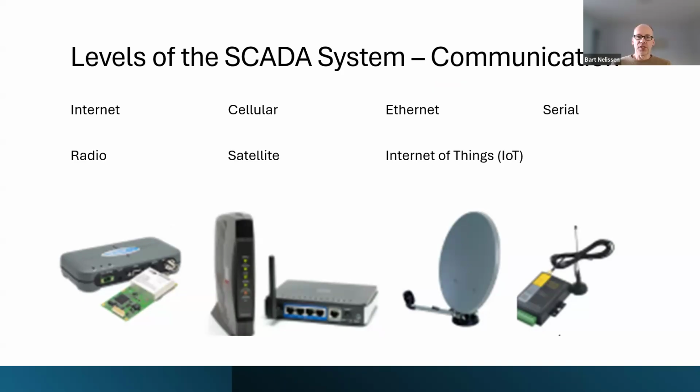You'll typically have on a SCADA system, for example, in a water type setup, pump stations, PRVs, water reservoirs, wells, what have you, all connecting from all these different sites into a centralized SCADA solution. All of these may have different mechanisms of getting that data from a remote site into the centralized SCADA system. So we can use hardwired internet, which is potentially the same as what might come to somebody's house or business. We can use cellular technology, because cellular, just like your smartphone, allows for data to be transferred.